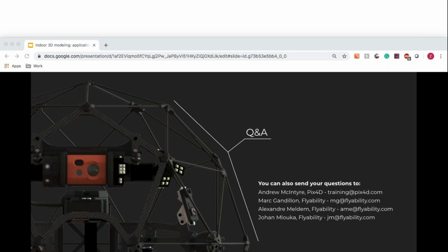But I think the most important difference between other technology and the ELIOS 2 is the ability of the ELIOS 2 to go in extremely tight spaces, and this is something that you won't be able to achieve with another drone technology. I was showing this ring where you had the refractory missing on it. This is just a portion of a vertical pipe that is probably 50 meters high or something around that, and it has a diameter of 50 centimeters. So even other technology would not get inside the pipe, and we're not talking about flying safely up to the top and going down.